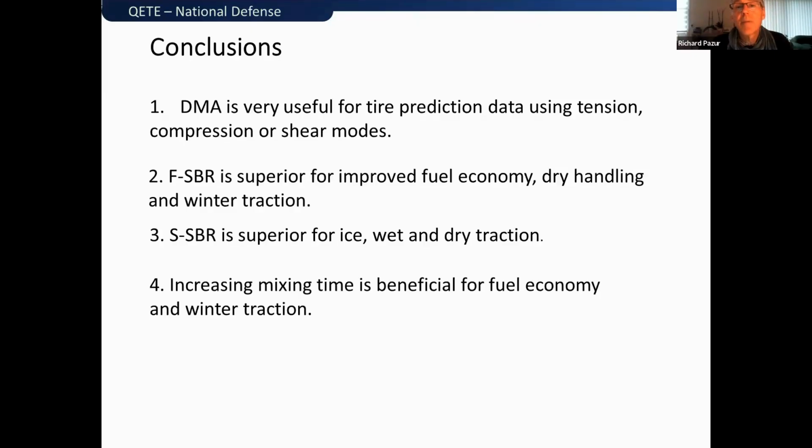Increasing the mixing time is beneficial for fuel economy and winter traction. And so why is that? Increase the mixing time, more silanization, more bonding between the silica and the chains. That's going to reduce the hysteresis and give us a lower tan delta and better rolling resistance.